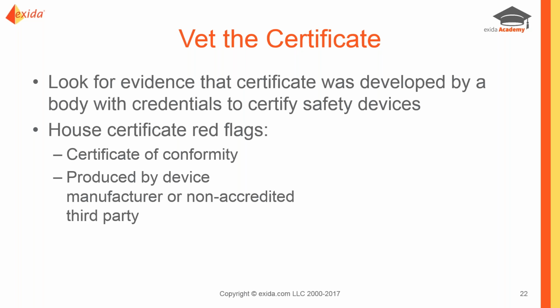All certificates for SIL certification should be done by a certified credentialed body. So if they're not, we put these in a category we call house certificates. And some of the things you might see on the house certificate, they'd be called a certificate of conformity, or if they are produced by a manufacturer or a third party that is not accredited for SIL certification.